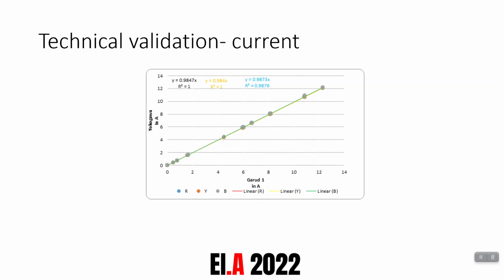So though this data set is of 19 days, we had actually collected 1 year current data, and we compared the monthly electricity bills with our Garud monthly average data. Before deployment also, we've checked the device's data for precision by testing it against accurate standard meters. One meter we've used is Yokogawa WT330 for laboratory reference, and the other one is Watnor WNC, and it was used as a field reference meter.